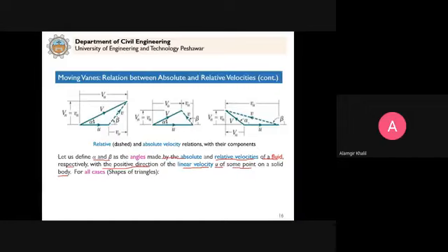In this diagram, let's say we have a vane, the fluid is coming and entering this vane, then it flows over the vane, and then it leaves the vane. So there can be an inlet velocity diagram and an outlet velocity diagram, and the vane is moving with a velocity u.